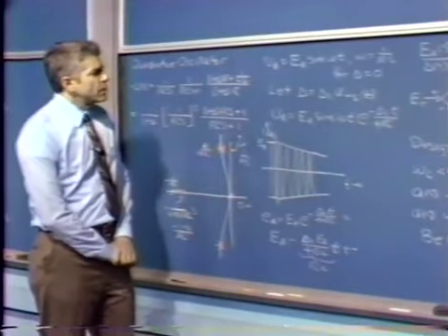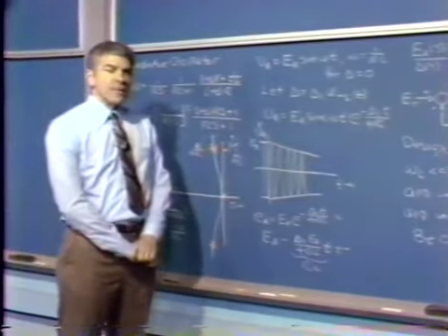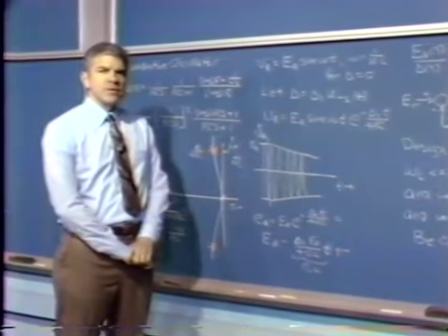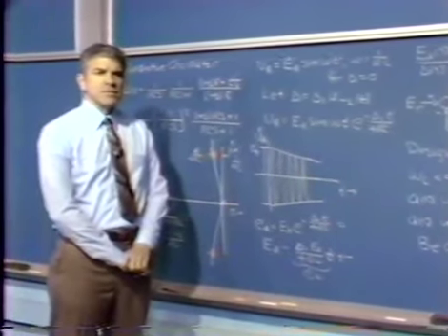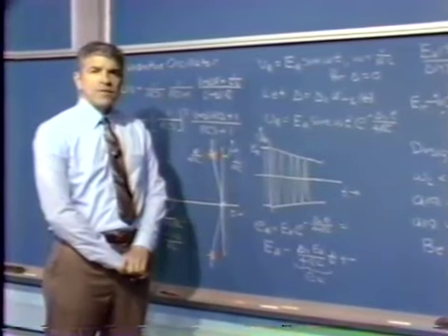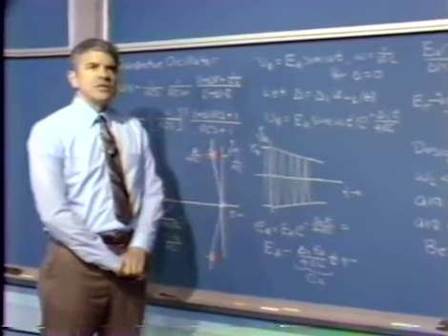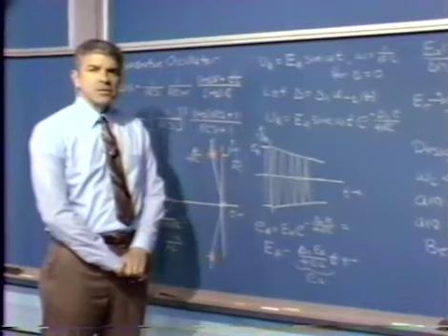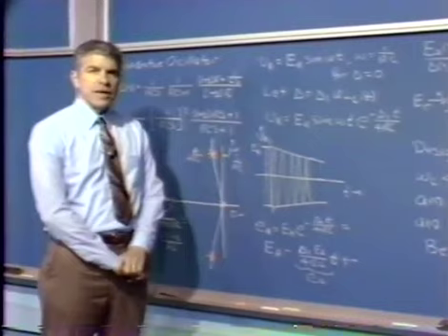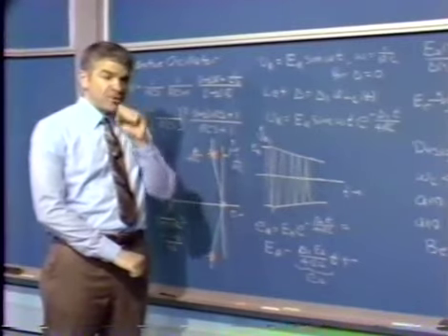Well, let's see how we really control the amplitude of this oscillator. I've mentioned the overall strategy, but now we have to think a little bit about how we model this system. In particular, one of the variables is how does VA, the signal amplitude, or actually the envelope of the oscillation, react as we change delta.